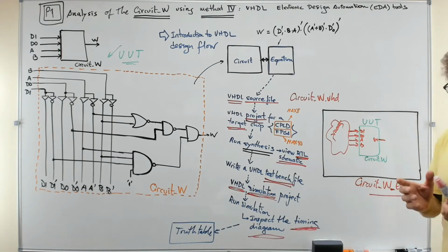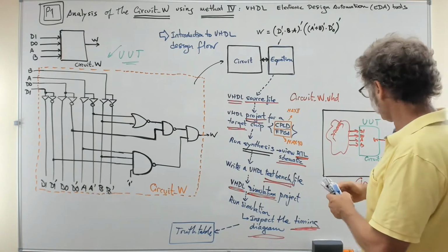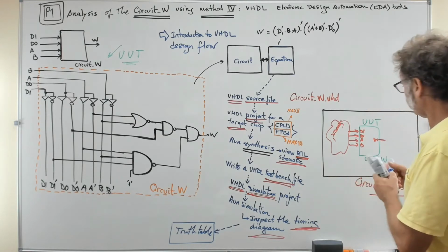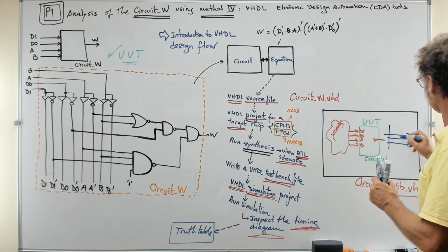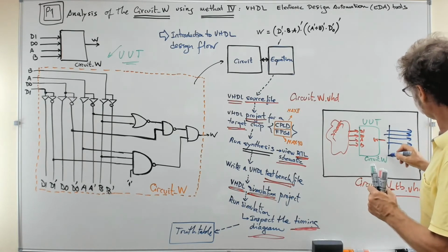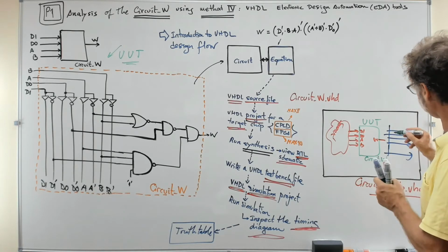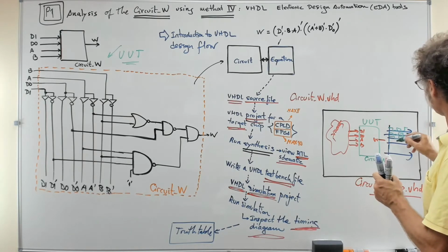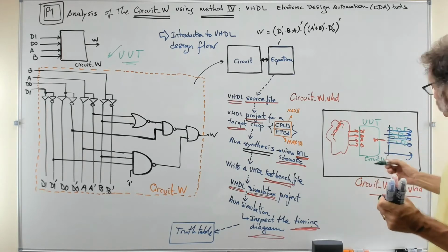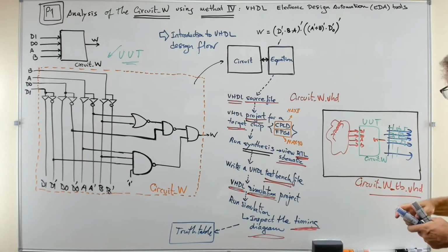So to watch this timing diagram, we have here another tool in the output. In the output we have to have the set of inputs and the output as well. So this is what we are going to do. We are going to apply a stimulus to the inputs, whatever they are, if possible the full truth table, and then in time we will see what happens with the output.